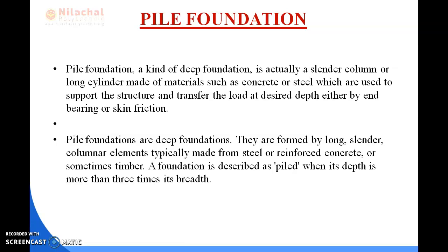Okay. Next come to the types of deep foundation. Basically it is of three types: caisson foundation, well foundation and pile foundation. So first we discuss what is pile foundation. Pile foundation, a kind of deep foundation, is actually a slender column or long cylinder made of materials such as concrete or steel, which is used to support the structure and transfer the load at the desired depth either by end bearing or skin friction.